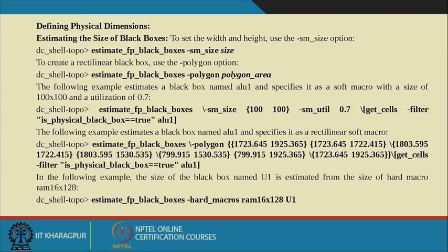So what is my primary target here? Now I am creating the macro blocks which will be used for further design. Whenever I want to use these IPs for a high level of design, I can mention all this timing information and all this physical information about that particular cell, and after that I can reuse those blocks in further parts of my design.